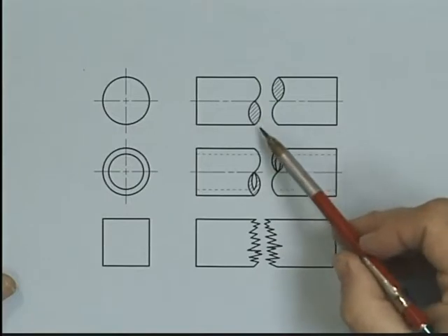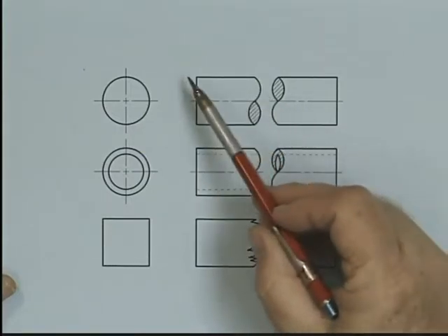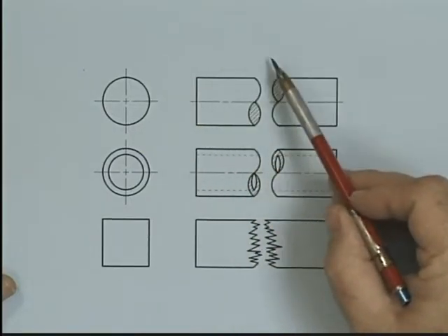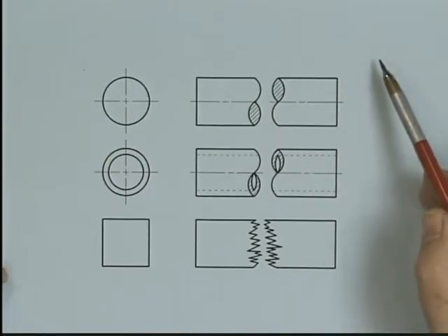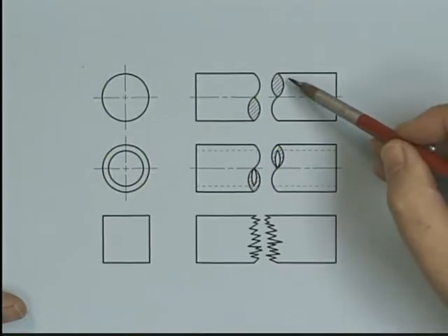The lower part's crosshatched. If we were dimensioning this, you'd see a little zigzag in the dimension line to show that this is not to scale. This thing is really continuing a long ways out here. Now, this is for the conventional break for a solid cylinder.